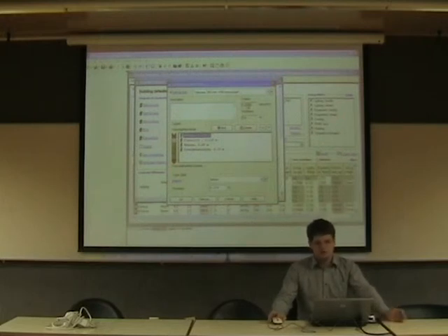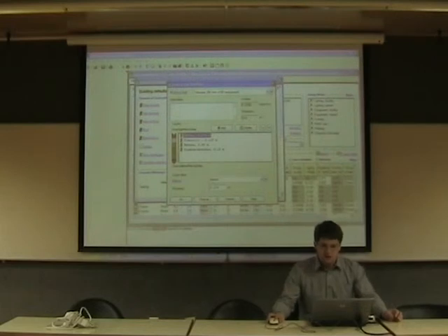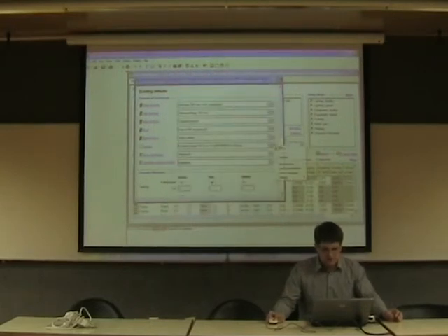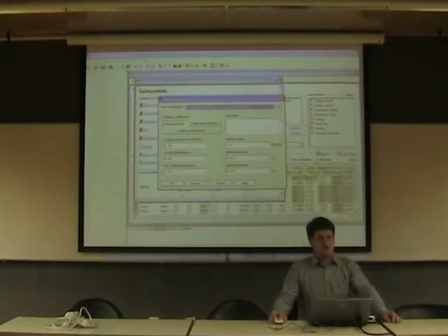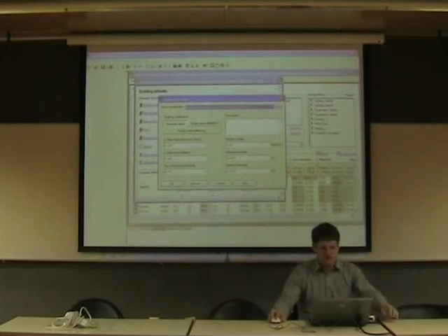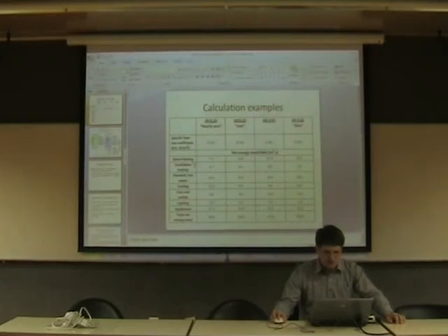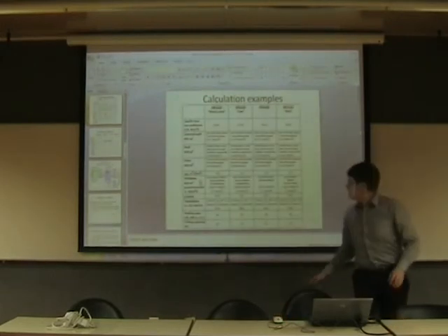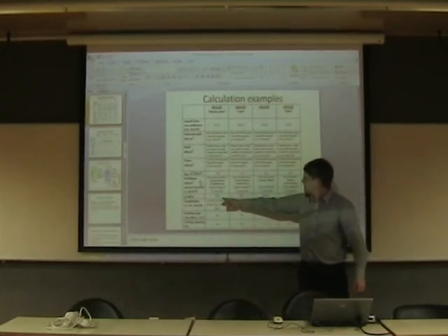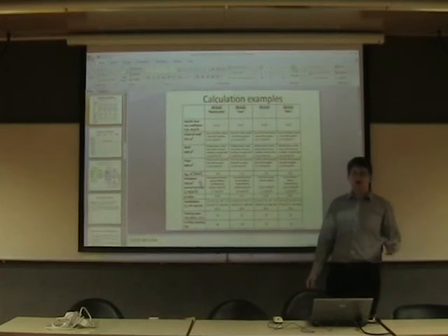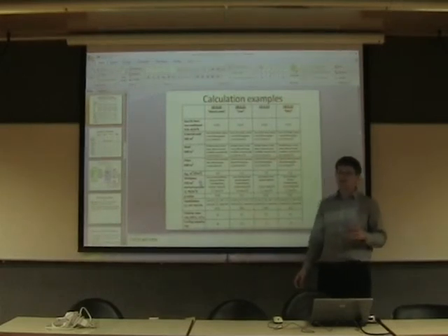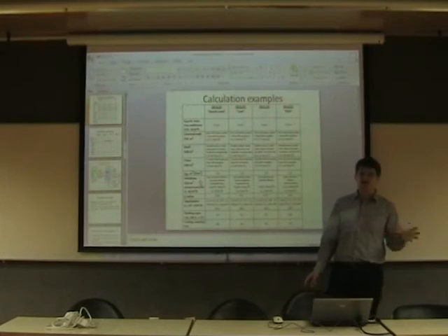This U value is 0.2, but this glass has a G factor of 0.56, which is a little bit too big in this case. It must be 0.46 or a little bit less, because when it's bigger, solar heat comes in easily and we have overheating problems.